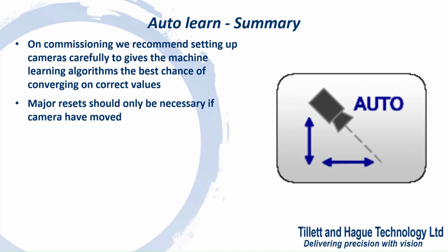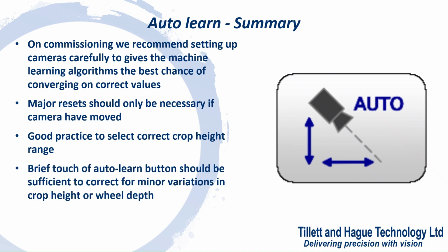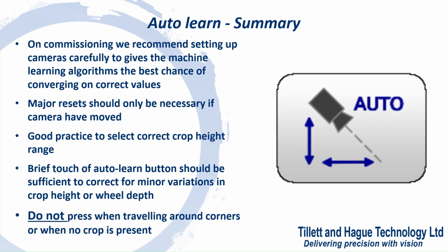It is best practice to set crop height to the appropriate range within the setup page to match actual crop height. Pressing of the Auto Learn button while in work if you think template match could be improved is normal, and should add enough flexibility to account for variations in crop height, implement settling into work, changing wheel depth, etc., but should not be pressed if the implement is travelling around a corner, or if crop has failed, as this may lead to the system learning incorrect values.